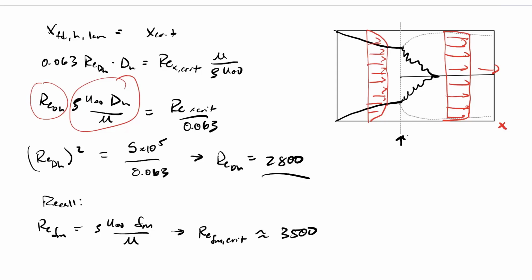It'll grow until this point where you meet the boundary layers, because in the turbulent region, the turbulent forces are not going to change as a function of position anymore because they can't grow. The viscous sublayer is trying to grow due to molecular diffusion.